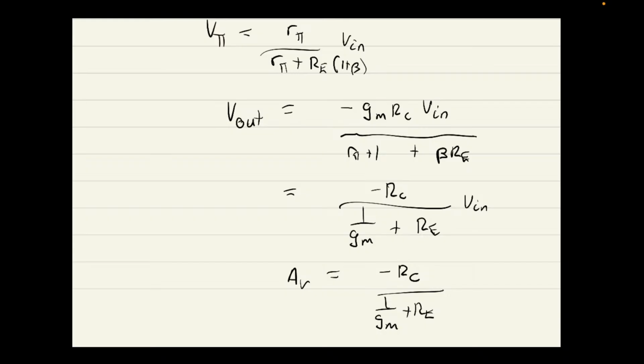If you notice, this is less dependent on gm. Small changes in gm can arise due to temperature. So it's good that Josh introduced you to that equation. If you remember, I_B is I_S times e to the power of V_B on V_T. So that means certain parameters in your transistors are dependent on temperature, and this makes it less so, which is great.